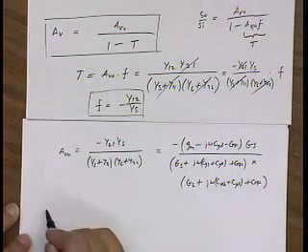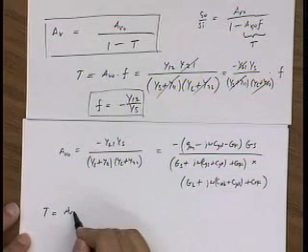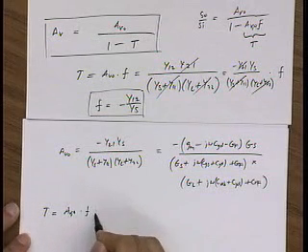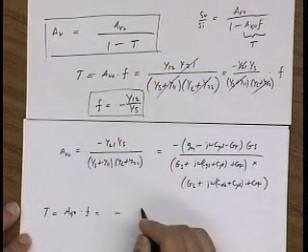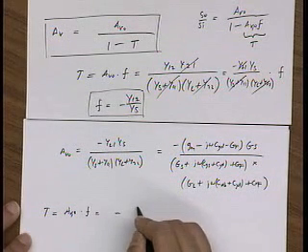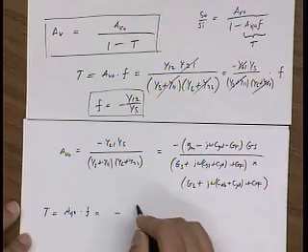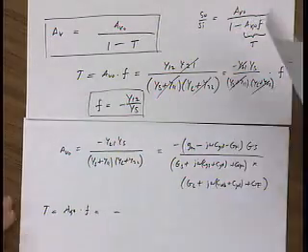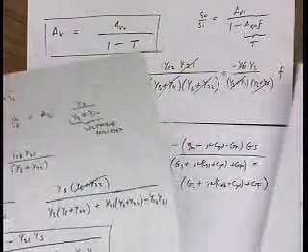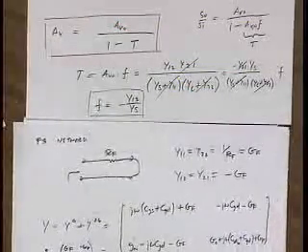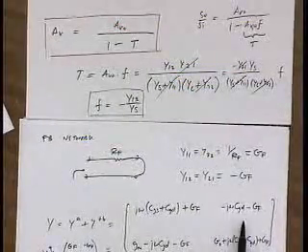And so then the loop gain is AV0 times F, so it's this term times minus Y12 over YS. Y12, remember, go back and look here, it's just C gate to drain and GF. So here is the calculation. So here is the Y12.